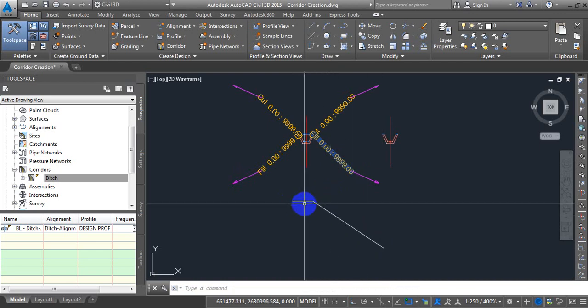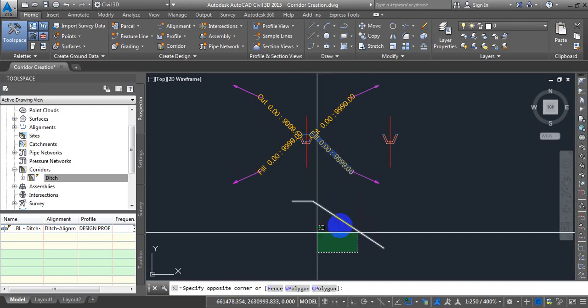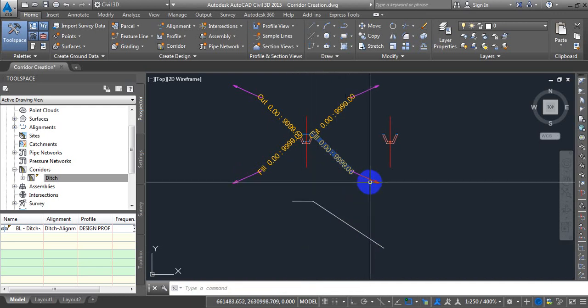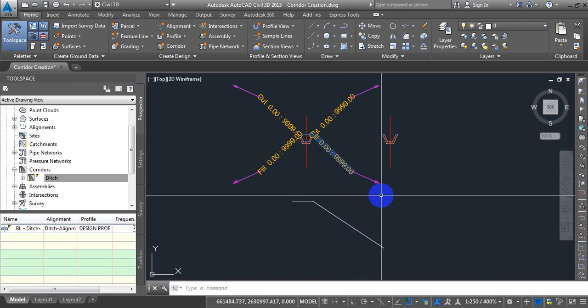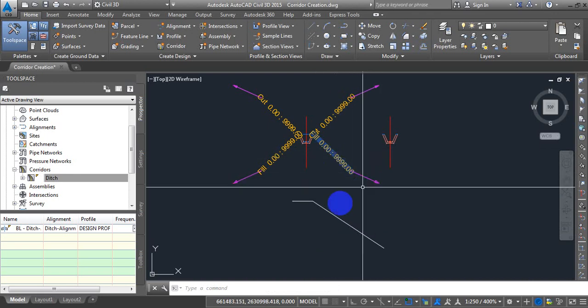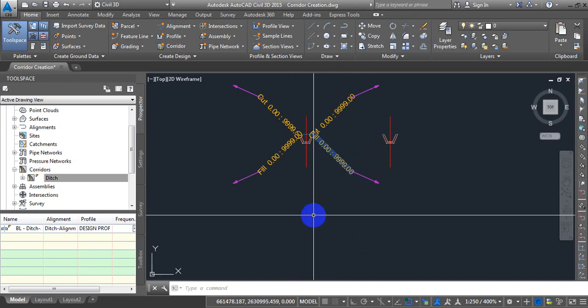They should have a small berm, and then I need to have a slope. Already we have this when my conditional subassembly is in fill condition, it will automatically add that slope to it, but there is no berm and I need to add a berm to it. How can I do it?